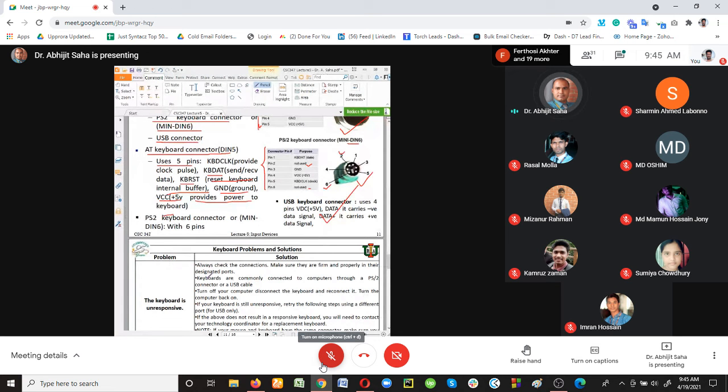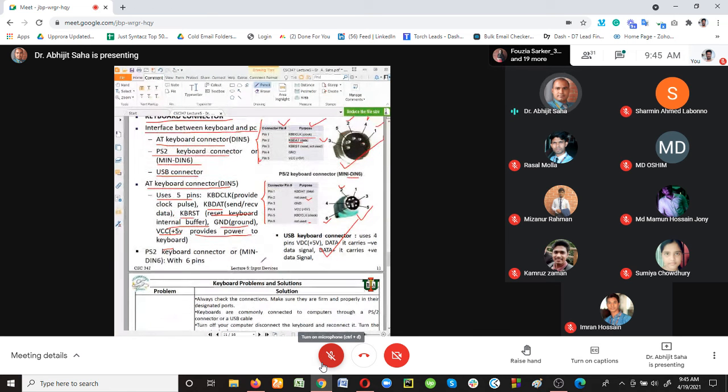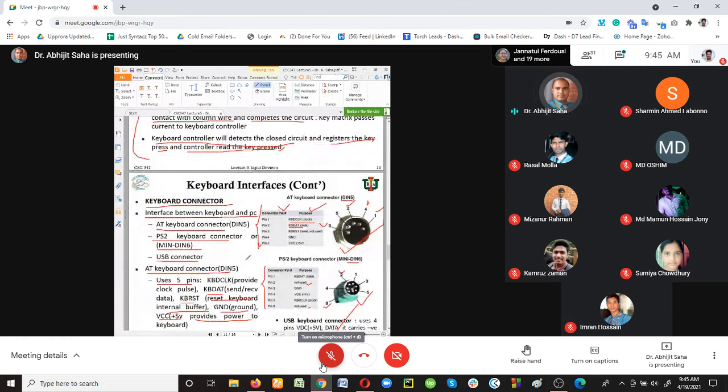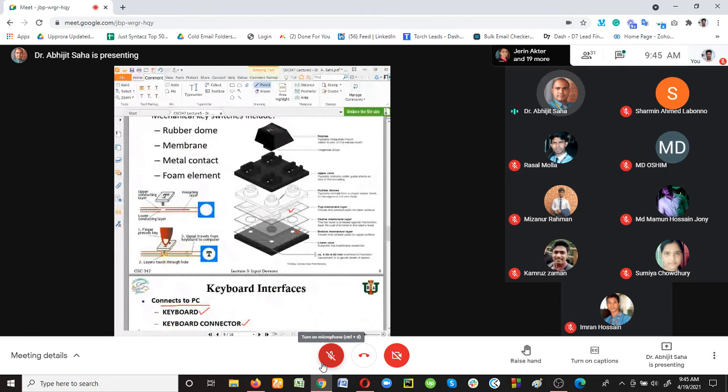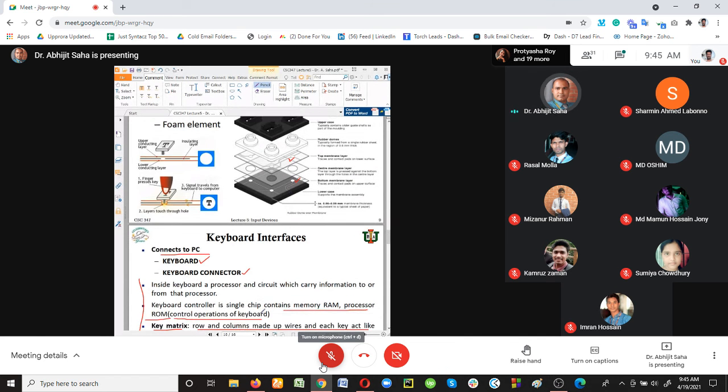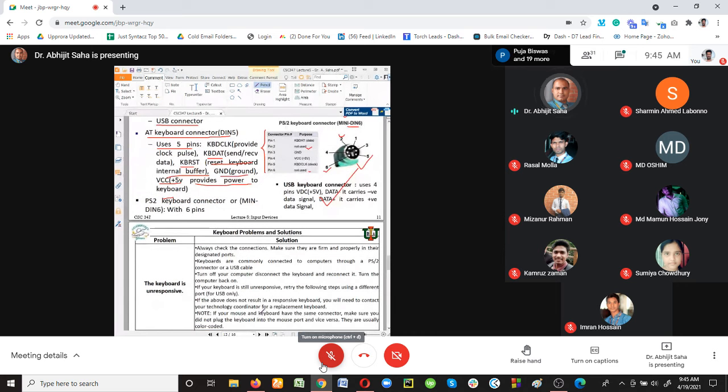So when it goes inside the keyboard, the dust makes some trouble inside the keyboard. Because when you are pressing the keys, it is really important that the two layers we have, the top layer and the bottom layer, with the row and column circuits, make contact. So it happens that when you are pressing the key, it is not getting the connection between them.